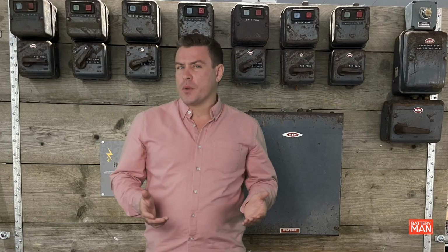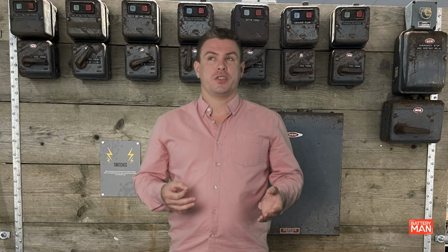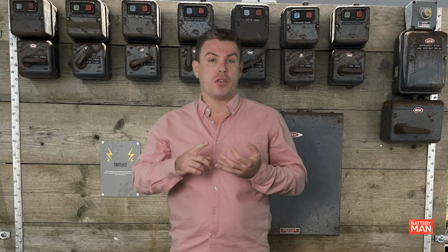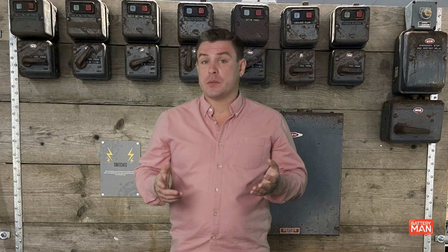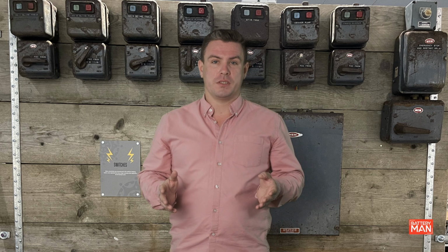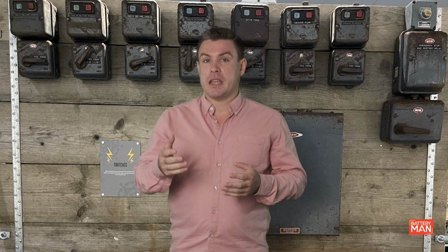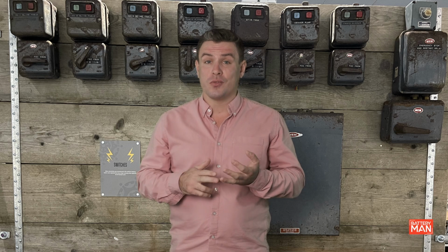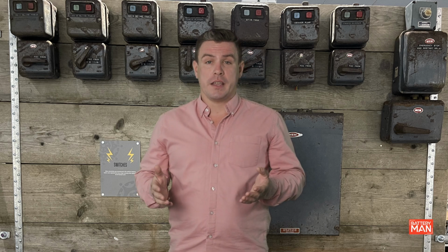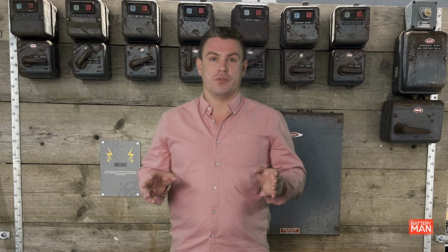A few weeks ago we looked at some of the tests that an electrician would carry out on a dead system, which gave us the values such as R1, R2 and Rn. This week's training reminded me why the continuity of a ring is so important. It's not just for an annual test or inspection, but it's to make sure that a circuit has been installed or is operating correctly. For example, say you leave a property that you've just installed a ring on.